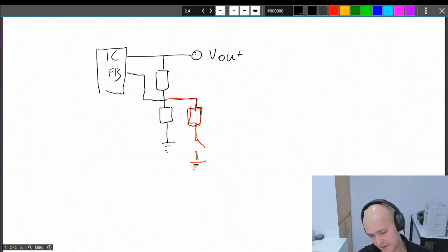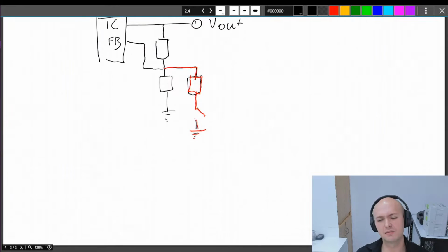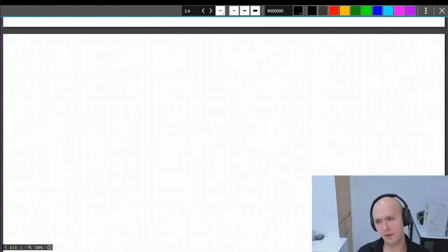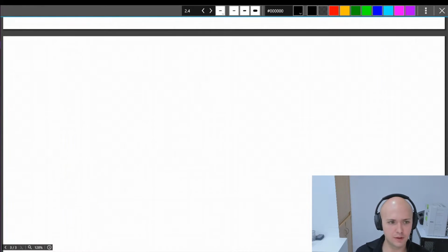I said that it would be a lot of hassle to add support for digitally controlled 5-volt LEDs. I came to the idea, actually it's not that hard. I will tell you why. Because we will have a switchable power supply anyway. So we'll have 12 or 5 volts at our pin. A digital RGB LED has the following pinout. So that's our LED.